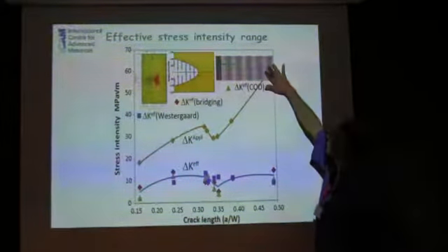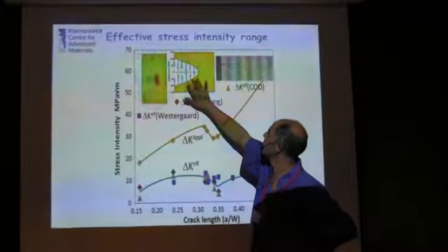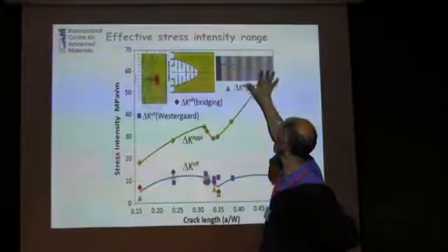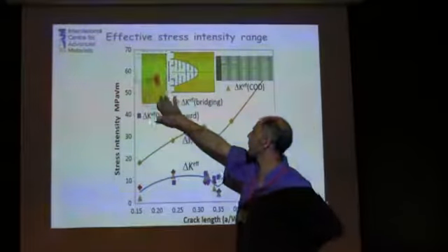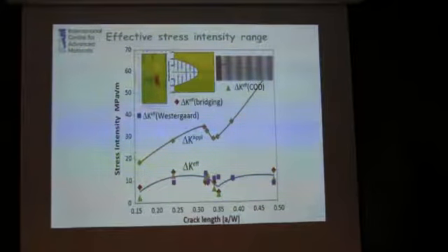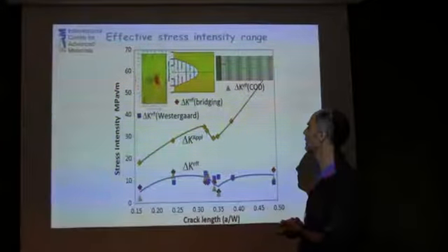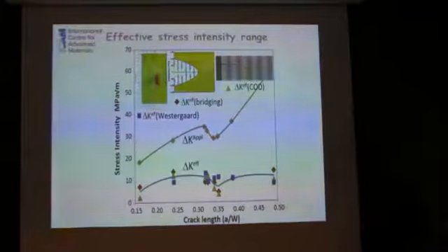We've done it from the crack tip opening displacements by measuring the crack opening. We've done it by measuring the stresses in each fibre as you bridge the crack and apply bridging tractions to the crack. So each of these core fibres is bridging the crack and holding it shut. And we've done it by measuring the crack tip stress intensity field in both phases and adding them together to give you the average continuous crack tip stress intensity, extracting the stress intensity factor, and we've done it that way.